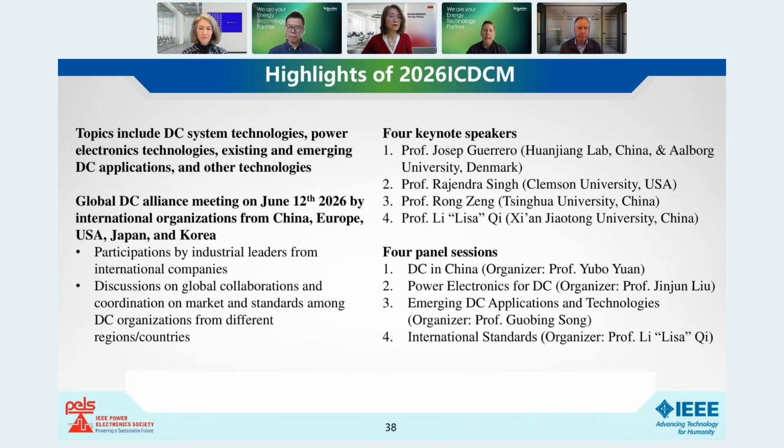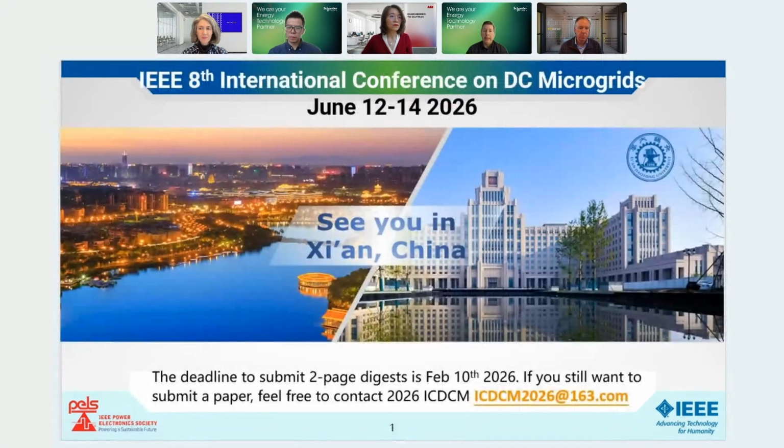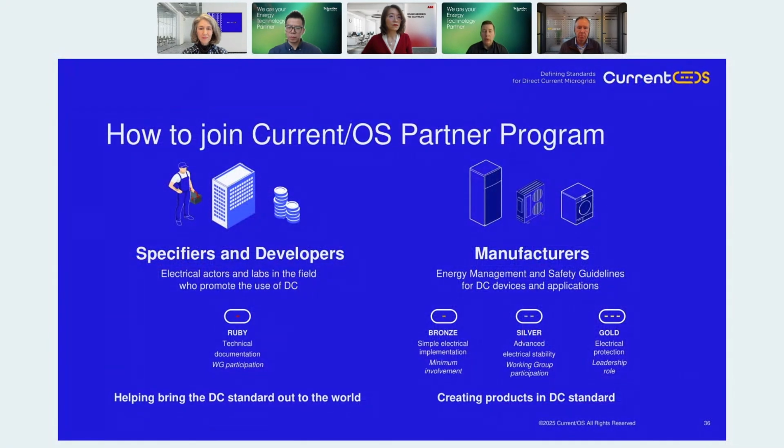And we can assume a maximum value of capacitances, usually on the order of millifarad, in order to understand the maximum current derivative by calculating the second order equation in our system, and according to that, we can design and select the proper solid state breaker.